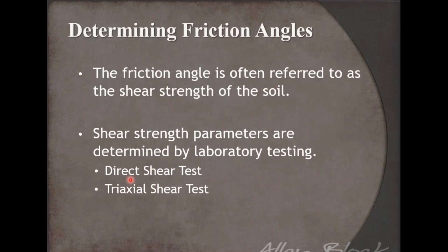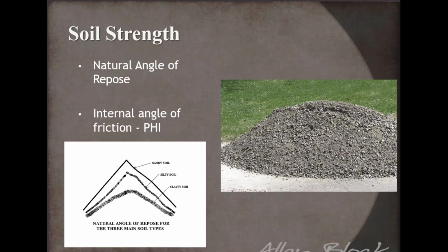We get into the friction angle, or the strength of the soil. The geotechnical engineering community will grab a sample of that soil and run what we call shear tests on those. That's the only true tested way that you can get what we call the friction angle, which is that strength of soil.